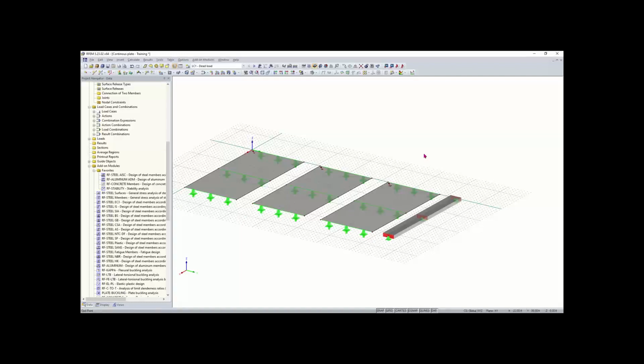And I would just add to that, just like what Alex said, the analysis is completely within RFEM, and all materials are available to you there for full modeling for the analysis. And then, as he mentioned, the modules are for design. Within the RF concrete modules, you would find the various standards, such as the Eurocode, the ACI, the CSA standard to actually do the reinforcement design, which is not done within RFEM. So I think that's good. Thank you. Thanks for the clarification, Amy. That was a good question.